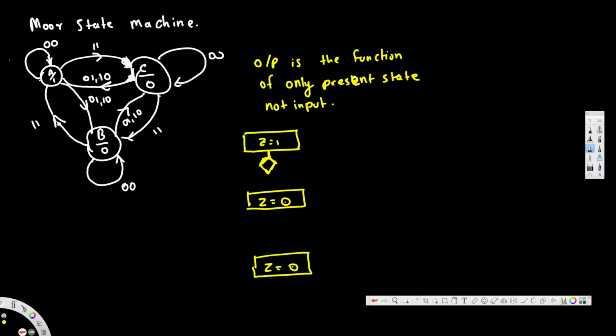Because you can see this has two inputs, so we will have X and Y. Before, in the Mealy state diagram, we had one input. If it's one input, it usually comes like this, 0 dash 1. But if they just put 1 1, it means it's two inputs. For most states, it's two inputs, so we have to put X and Y as well. And it doesn't have the conditional box because that only comes with the Mealy machine. Okay, now let's go ahead and continue.